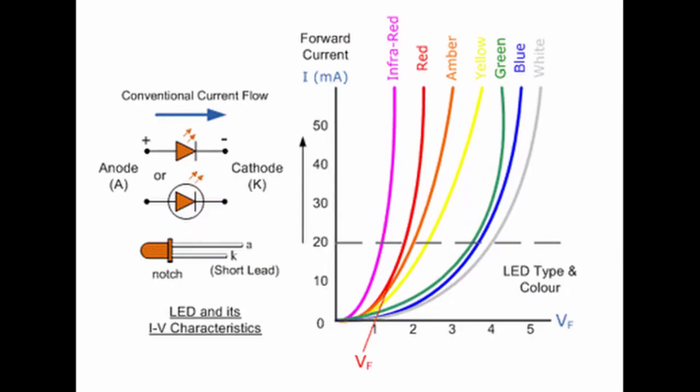Most common LEDs require a forward operating voltage between approximately 1.2 to 3.6 volt with a forward current rating of 10 to 30 milliampere, with 12 to 20 milliampere being the most common range. Our LEDs vary vastly in how much voltage is needed to perform spot on with maximum brightness. It was decided to use 220 ohm resistors in our testing. With the available resistors, it gave good brightness through LEDs of all colors.